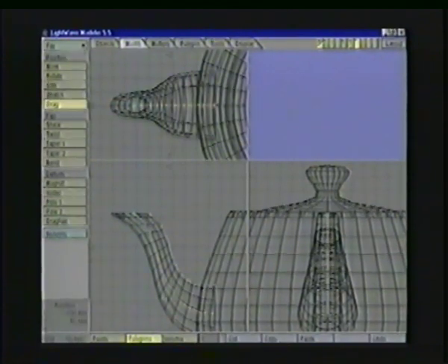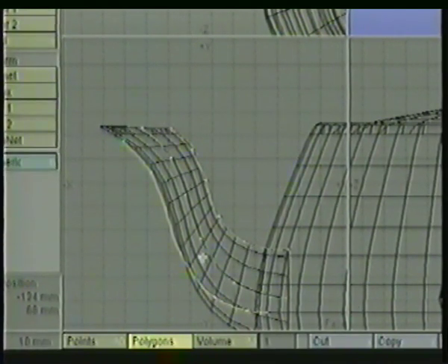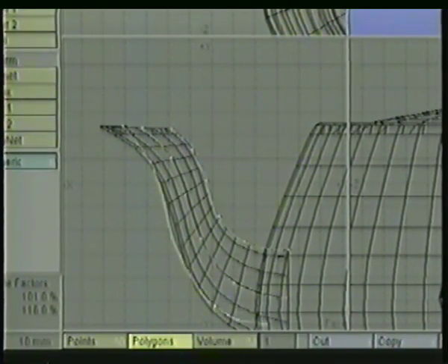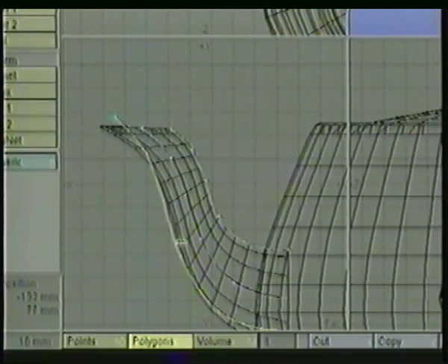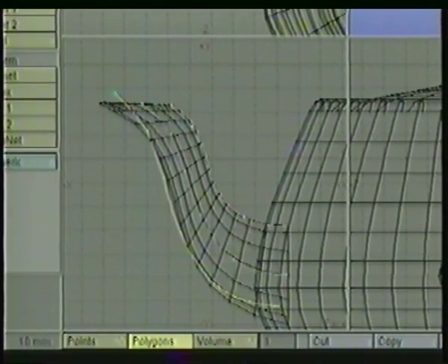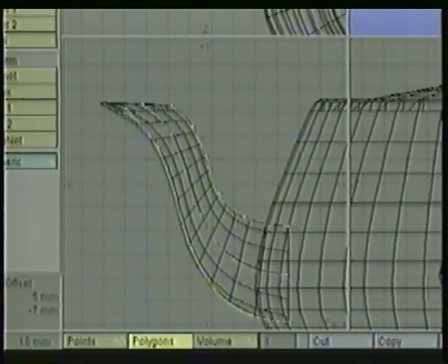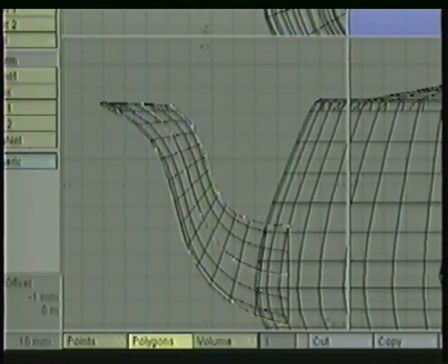Once again I'm going to make sure it's selected, copy and paste it, go to move and drag it over to the other side. I want 3 splines total. Once again, I'm going to hit H on the keyboard for stretch, and I'm going to stretch it up and over to the right a little bit. Now, it may be very difficult with the stretch tool to get exactly to the right point, but it'll get you started much faster than dragging all the points individually, and now it leaves me a little bit of cleanup with just a few points being dragged around and into position.